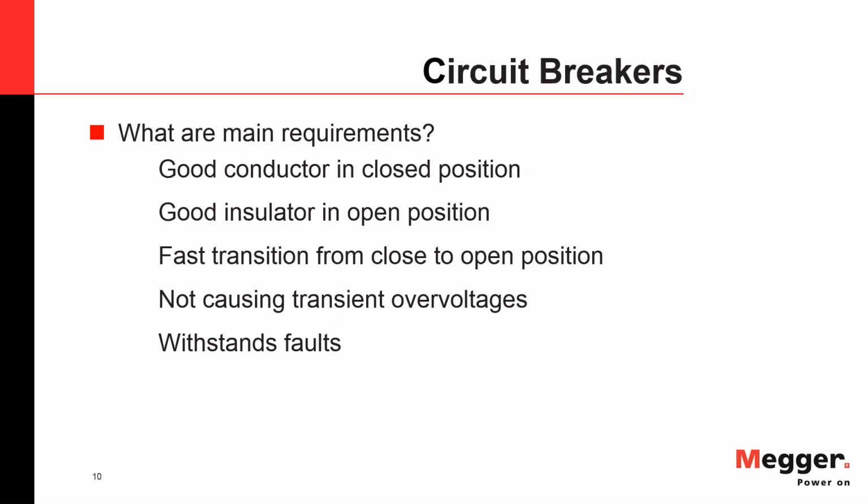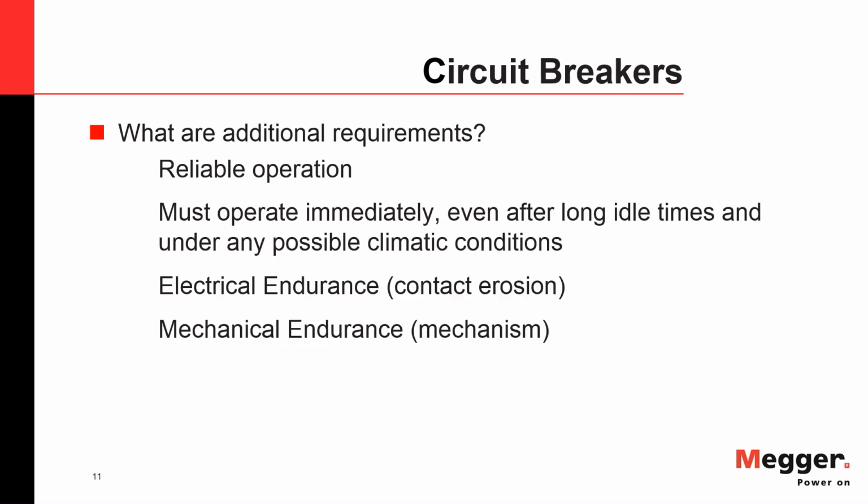When it interrupts the fault, it should withstand the fault. A circuit breaker that is never operated but then needs to operate because there's a fault, and it explodes, that's not really the purpose of the circuit breaker. It should withstand the fault it's designed for. Additional requirements: of course, it should be reliable.